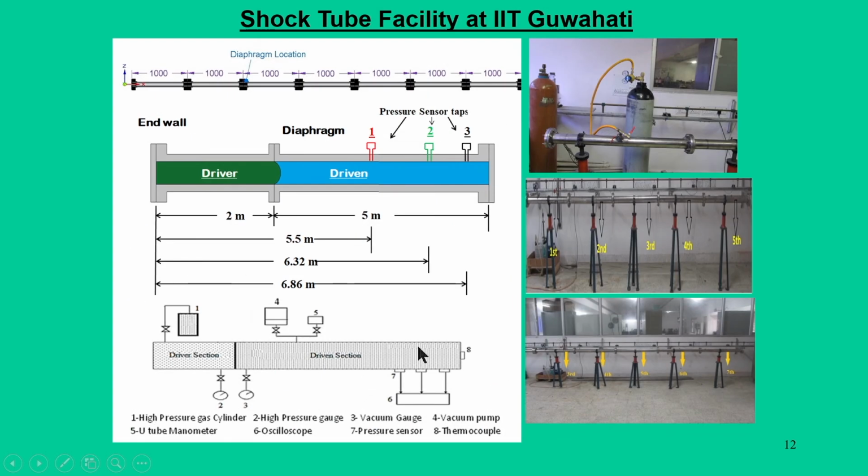Okay. So, this is all about the theory of these things. Now, I will just explain what shock tube facility we have in the premises of the Mechanical Engineering Department, IIT Guwahati. It is a 7-meter tube, driver and driven. You can see in this particular picture that the driver section is equipped with a high pressure gas cylinder,